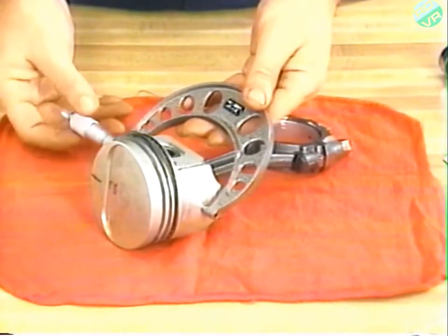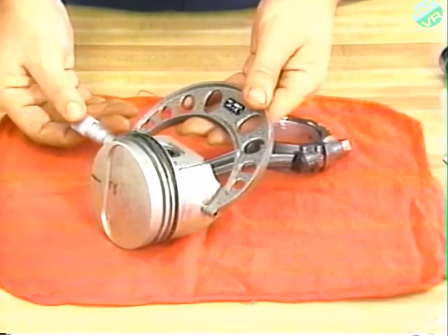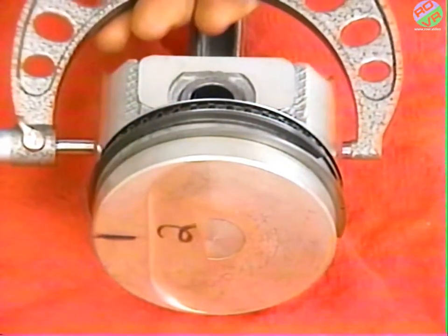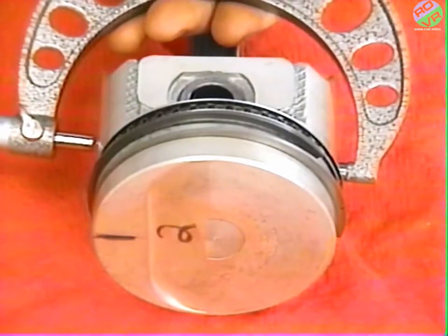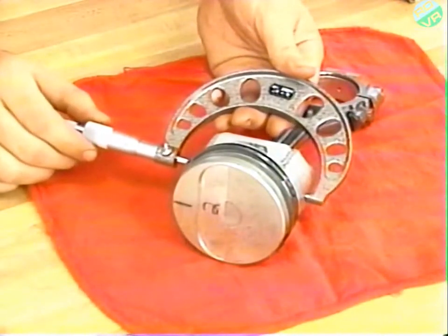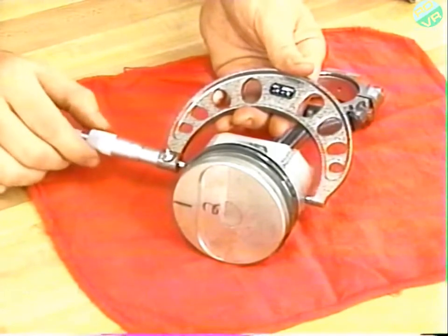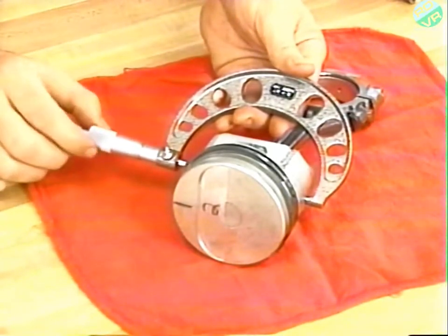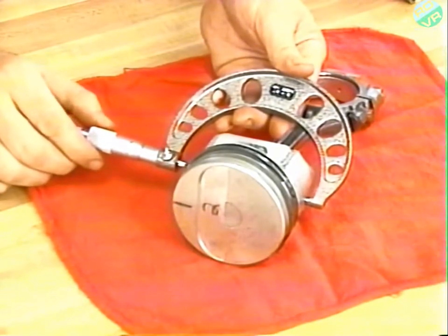With the other hand, use the thumb and forefinger to tighten the spindle. It's important to make sure that the mic is held at right angles to the piece you're measuring. If the mic is held cocked, you'll get an oversized reading. To avoid this, hold the mic loosely and gently turn the spindle down against the workpiece. Remember, the micrometer is not a C-clamp. Use a minimum of pressure.